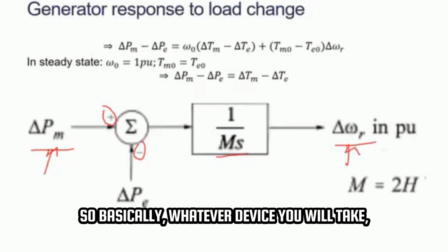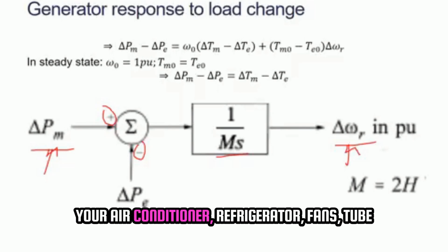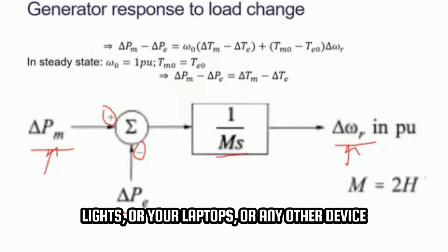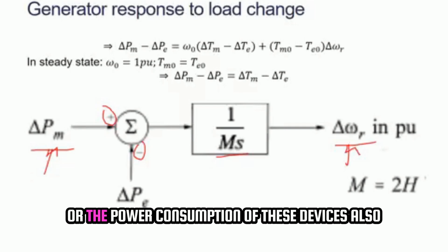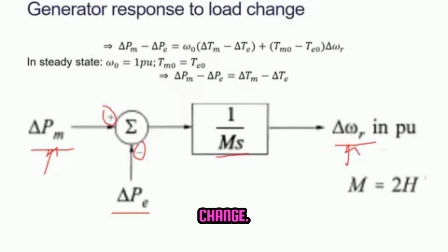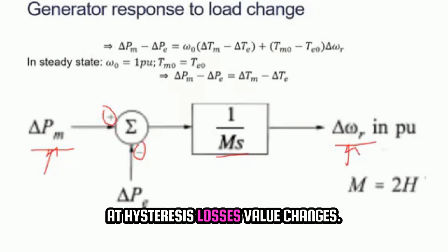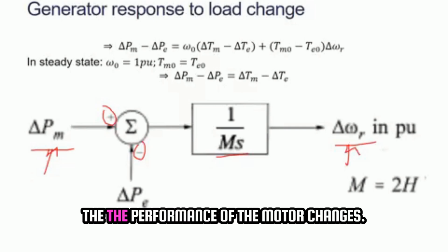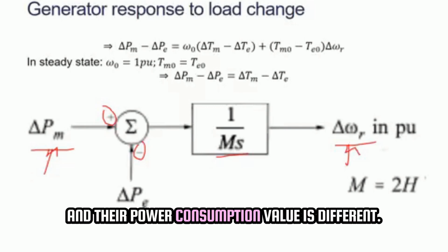So whatever device you take, either motor devices, air conditioner, refrigerator, fans, tube lights, or laptops, or any other device, if the frequency changes, the value or the power consumption of these devices also changes, specifically motor devices, because in the motor the eddy current and hysteresis losses value changes, and as they change, obviously the performance of the motor changes. Most of the devices are motor devices, so they start behaving differently and their power consumption value is different.